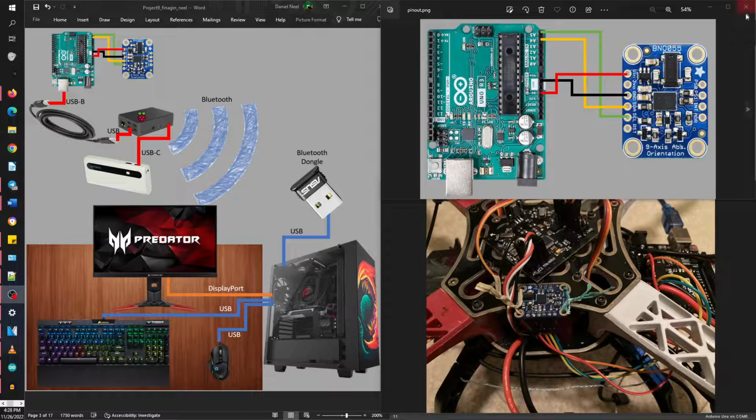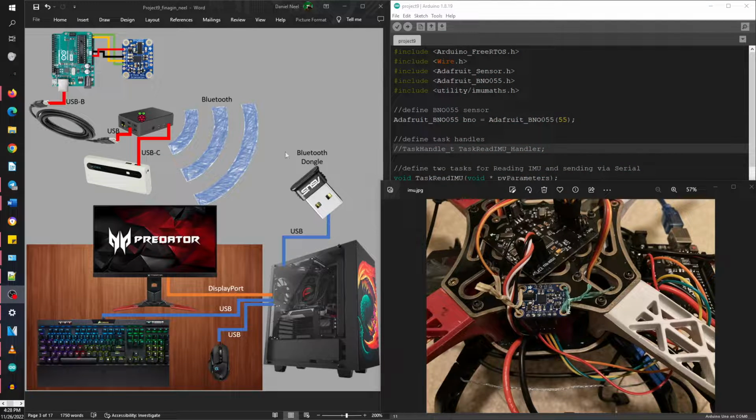The hardware layout is identical to Project 8, KK controller quadcopter design carrying a 5V battery pack powering a Raspberry Pi 4, Arduino Uno, and Adafruit absolute orientation sensor tied to the front. The key difference is the reliance on Bluetooth as a wireless transport layer rather than a 2.4 GHz Wi-Fi signal.